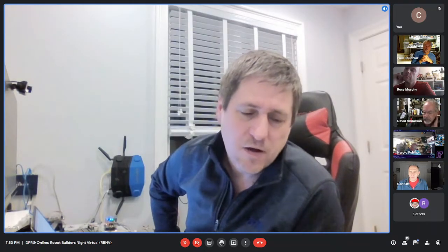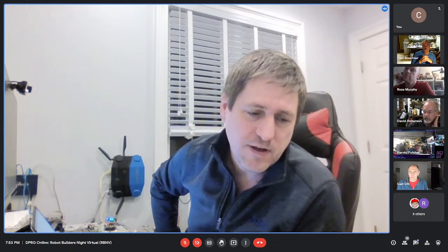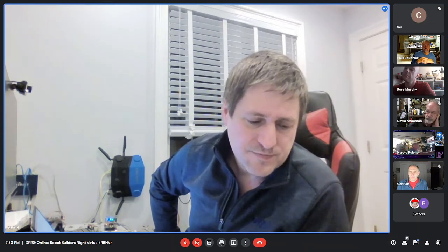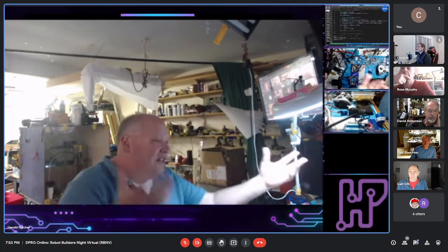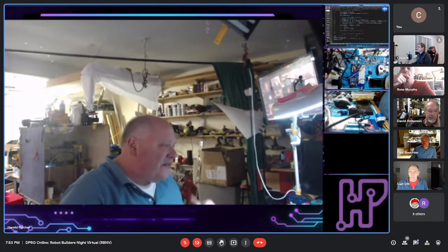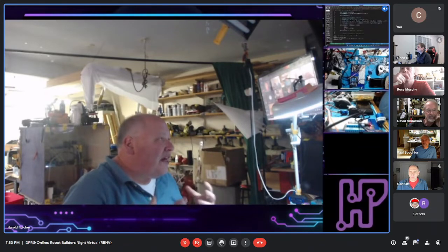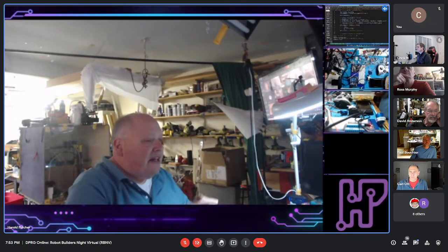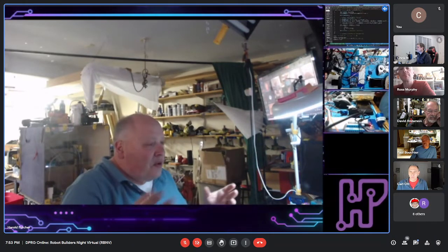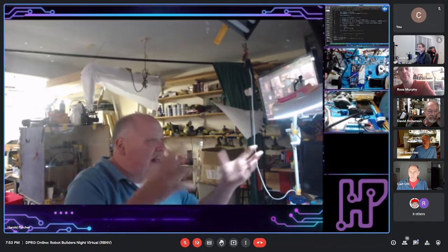The timing on the ROS 1 communication is just not controlled in any fashion. There's also high overhead, so there was not a lot of real-time capability in the way they were doing the communication. And as far as robotics goes, we have a bunch of async things that happen all over the place. With ROS 1, you have a centralized master that controls all of that communication. ROS 2 gets rid of that master, so every node sets up the network, so to speak, as it comes in. And as more nodes join, they just see more things that they can do and talk to.